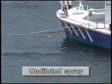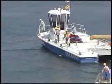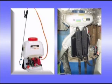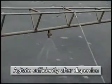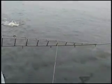Oil dispersants must be utilized in an undiluted state. They are never diluted with water. You must never spray an excessive amount on the spilled oil. The dispersant must also be sprayed on the windward side of the oil. During strong winds, spray the dispersant as close to the surface of the oil slick as possible. You should be very careful not to let the dispersant touch your skin. The dispersant and oil must be agitated or mixed up immediately after spraying. There are also some dispersants which do not require this.